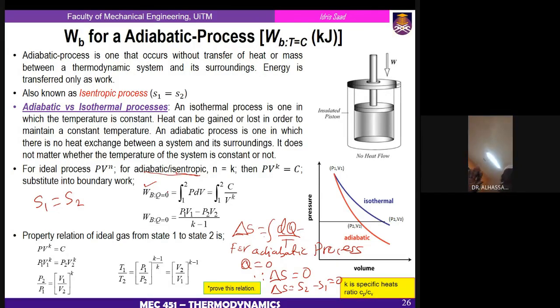You understand me? In chapter 1, we did look in detail, I explained what we meant by entropy. Entropy is the degree of irreversibility of a system, or the degree of disorderliness of a system. But in this case, we'll go more into the degree of irreversibility of a system. It means when a system is more and more irreversible, then the change in entropy increases. But under reversible conditions, the change in entropy equals 0.